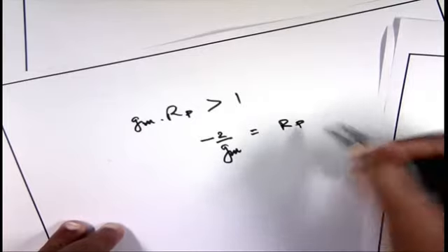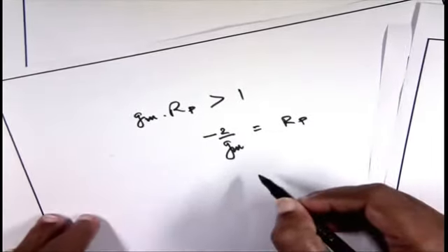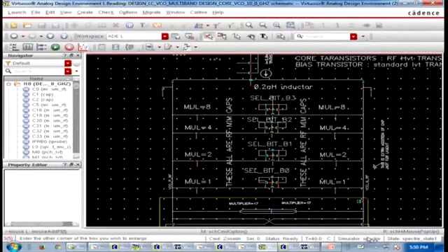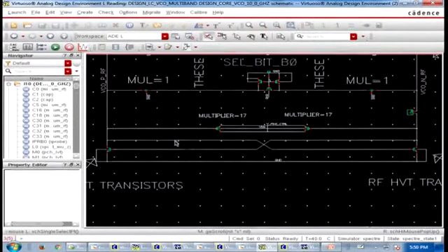But you have a current source, which is shown here. This is the cross coupled pair, one transistor and another transistor, both cross coupled to generate the negative resistance. Of course, the negative resistance is generated by the biasing condition, it's not a real resistor.